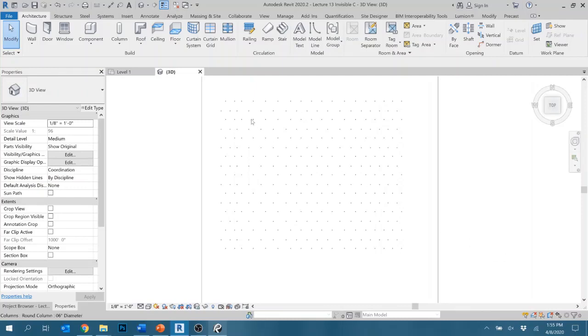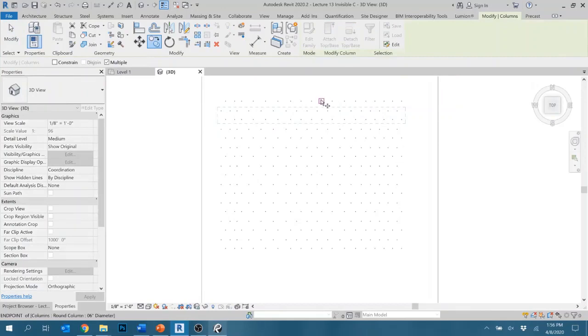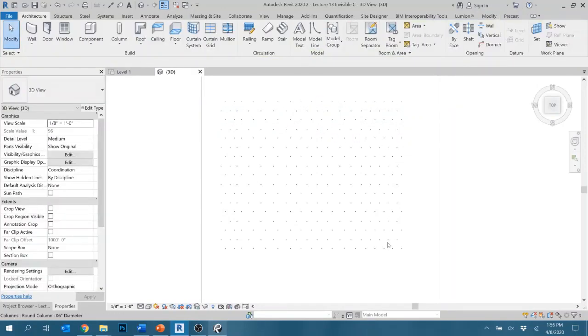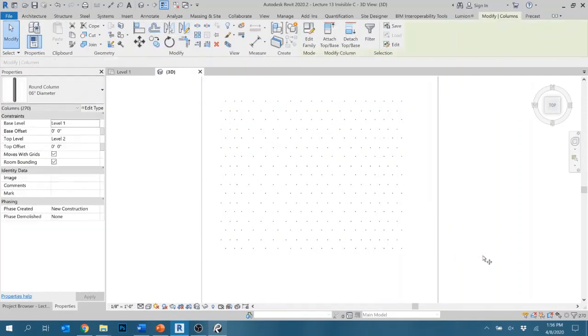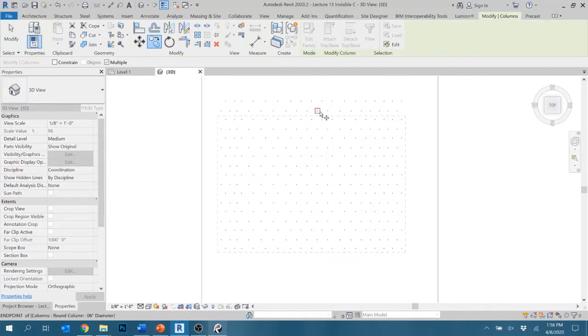I've drawn one organic column row, and then I shifted it 4 feet, 8 feet away, and using copy, what I did after creating the first 3 rows was to copy using the base point of 1 column to get the rest. So again, don't overdraw or repeat. That's what the Revit tool is for. So I can simply repeat that way.